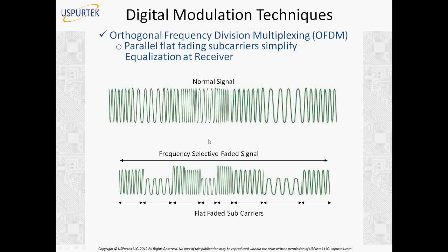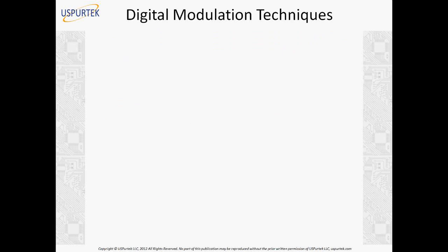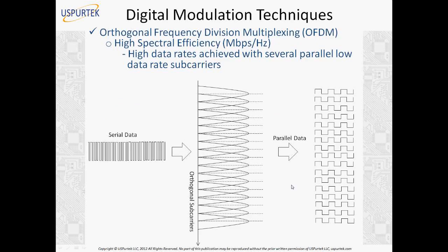So here we have a question. Here we reduce the bit rate, then how can we say we increase bandwidth? Okay, let's go back to the previous slide. Here, when we say bandwidth, we mean the bandwidth of the complete OFDM channel, all the subcarriers included. So you add up the bandwidth of each subcarrier, and that gives you the total bandwidth. So we increase the total bandwidth, not the bandwidth of one particular subcarrier. So total bandwidth is much more. It may be 20 megahertz, 25 megahertz, or 40 megahertz. But each subcarrier occupies only a very small band because it's carrying a very low data rate.